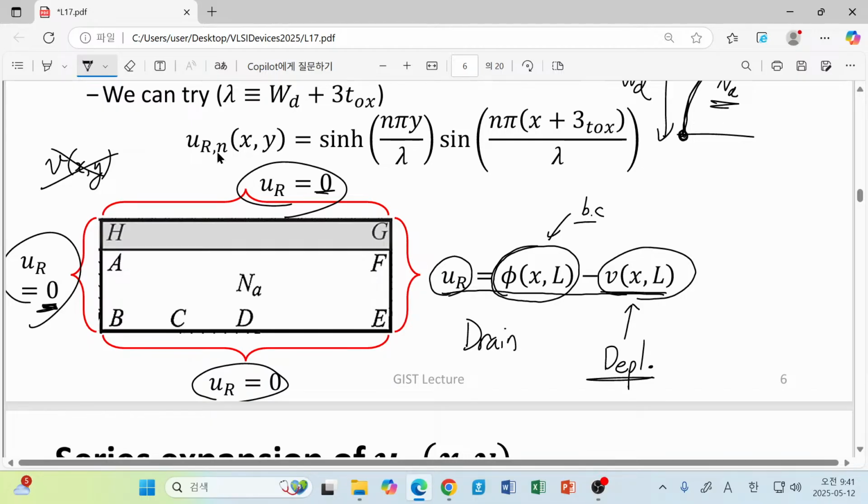But the boundary condition is a constant inside the silicon region due to phi bi plus our drain voltage. So if we apply high drain voltage, actually this value can be quite high. Please note that this is about 1 volt, but depending on your bias condition, if you apply 2 volt, then this value can be even about 3 volt, 4 volt. You can increase this number quite easily.